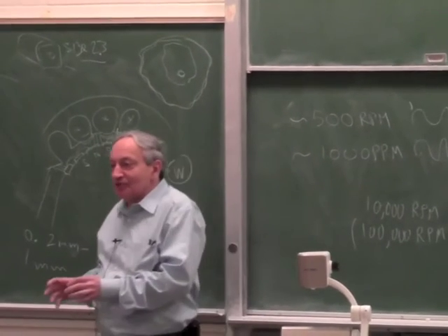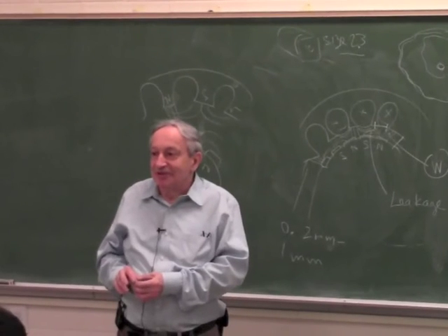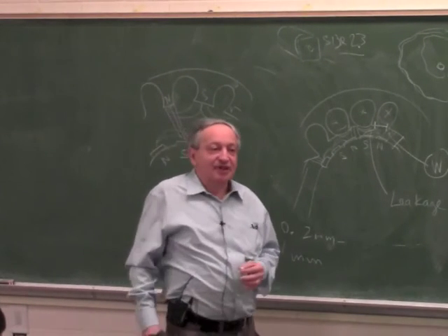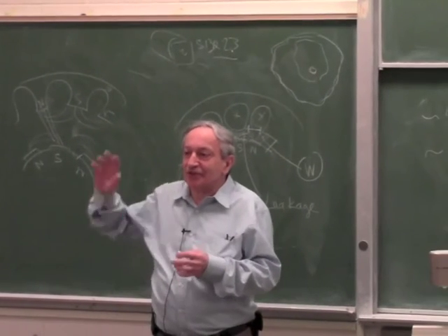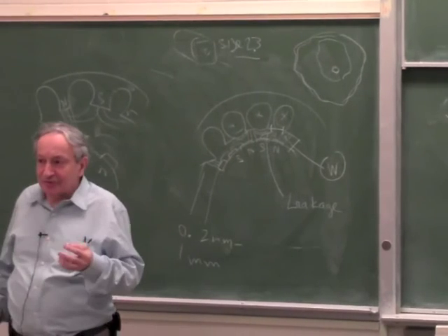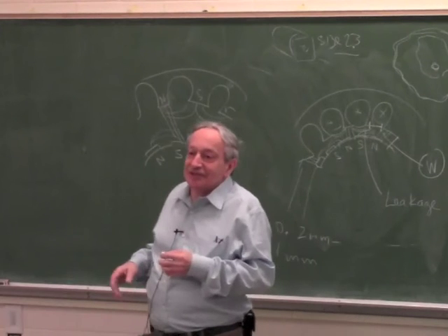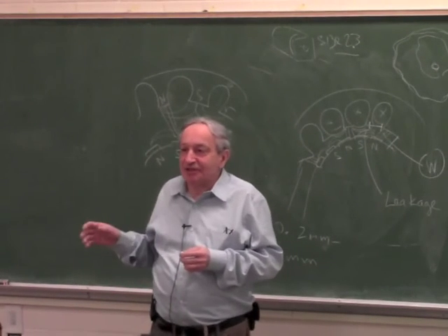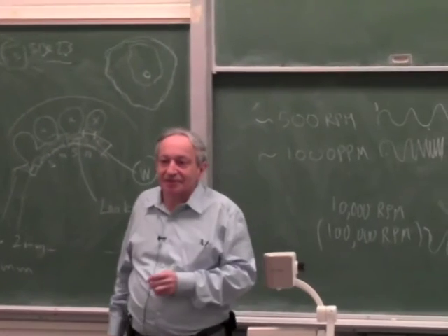It's not cheaper on a small scale. When you build a lab thing, a small thing, it's cheaper to use a stepper if you don't need the high speed. Okay? But if you build bigger machines, like a machine tool or a robot, you don't use steppers. Industrial robots don't use steppers. The original ones use DC motors, which are very good, because they have all the advantages you want, but they have sparks. Some modern ones use brushless DC or synchronous motors, but gear down rather than steppers.